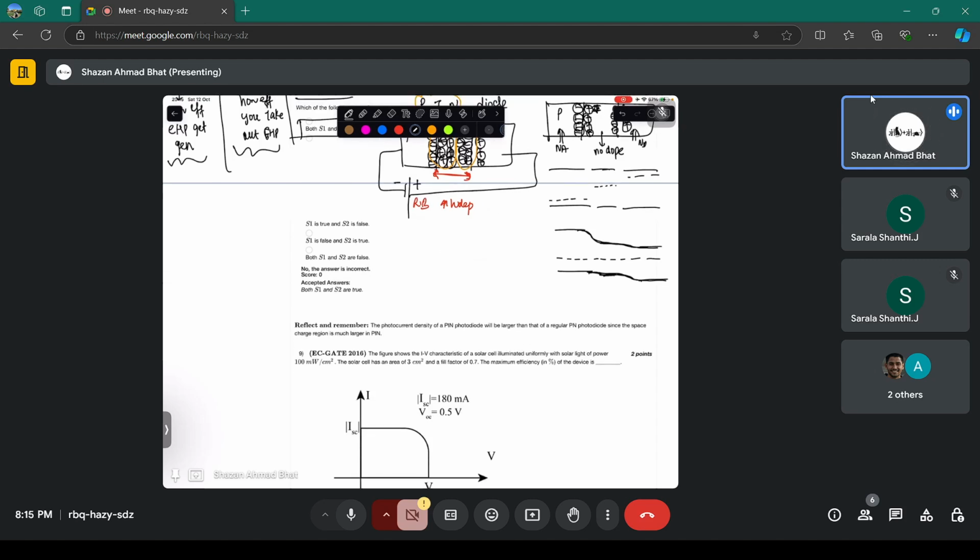So these slopes are necessary in order to separate the electron hole pairs. That's why I told you that a combination of different layers of materials is necessary, because they give rise to internal electric fields, and internal electric fields give rise to separation of the electron hole pairs. And you see that here this is P type, this is N type, and the intrinsic is exactly in the middle, at least at equilibrium. The non-equilibrium scenario is different. In non-equilibrium, you get the quasi-Fermi levels.